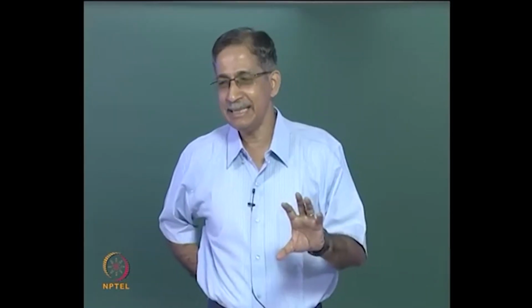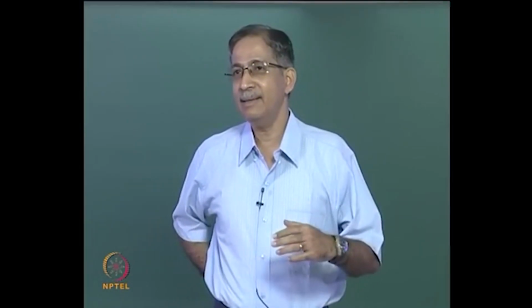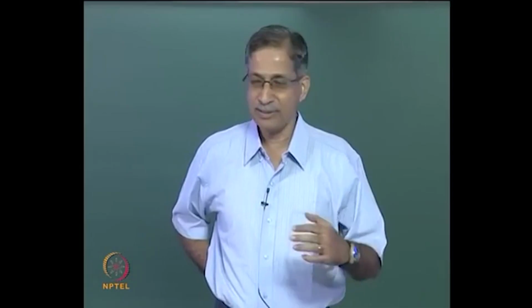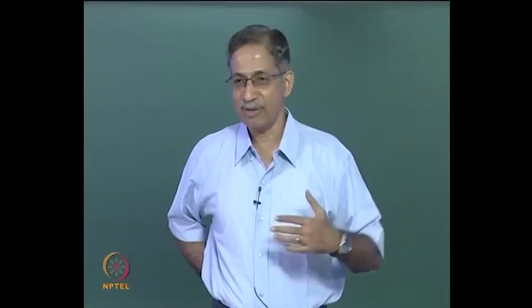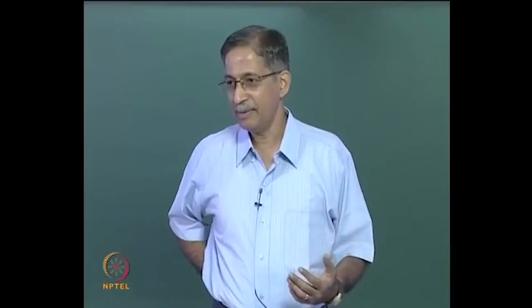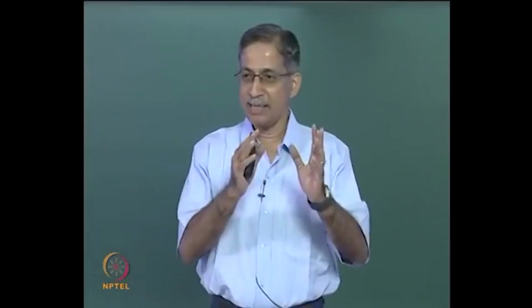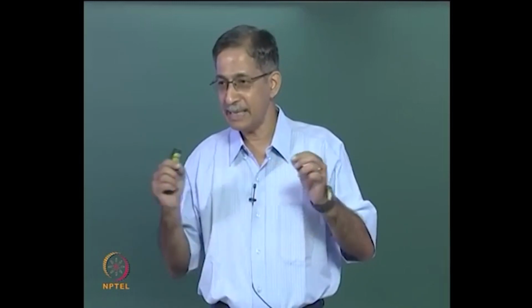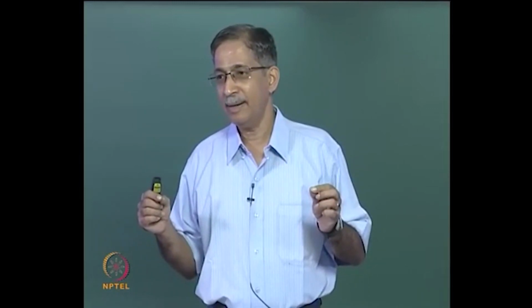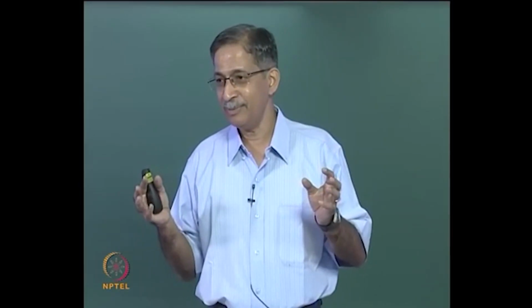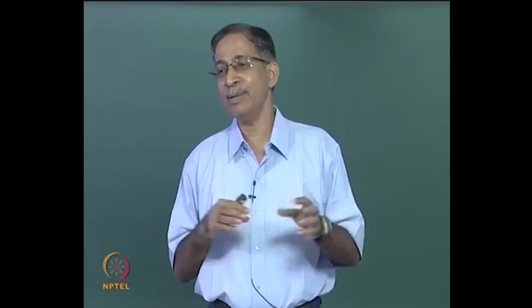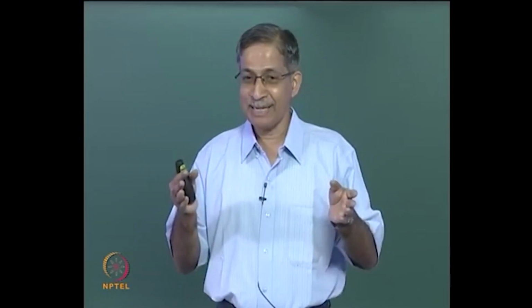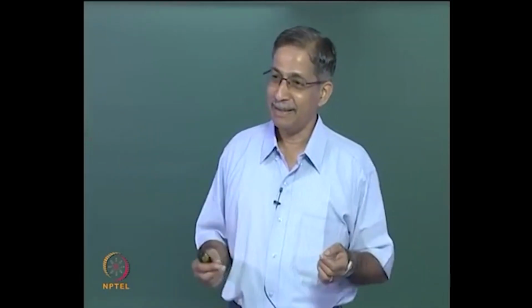We are now digging a little deep into the subject. You will find that finite element analysis, which is something you will study in an advanced course, uses such displacement functions to develop the theory. Okay, you have a complicated structure, you break it up into small parts, they are called finite elements, and you try to reduce your degrees of freedom to the movements at the ends of the element, and you have to interpolate to get information within the element, and if you are lucky you have got an exact formulation, in which case you get an exact solution.